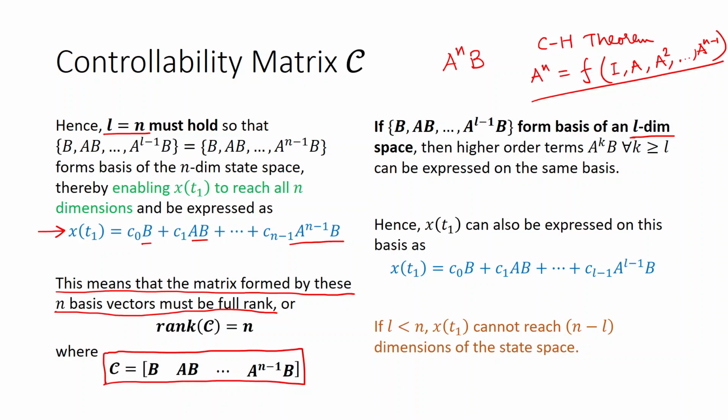Very easy to remember the formula, a bit more difficult to understand why this formula will work. So the understanding is what I try to make you go through. You must remember why the controllability matrix needs to be full rank in order that the system be reachable. We are testing reachability, please remember that. So with this, we are very sure that if the controllability matrix is full rank, I will be able to reach anywhere in the state space.